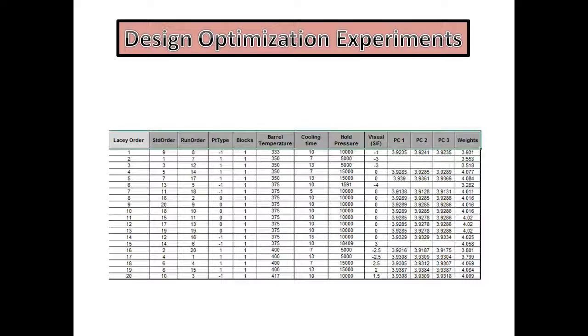Something else that should be noted is that oftentimes when you're making this type of multiple changes, it's a good practice to drop your shot size to 80%, make your changes, and then add shot size and reduce cutoff to get back to a full part.